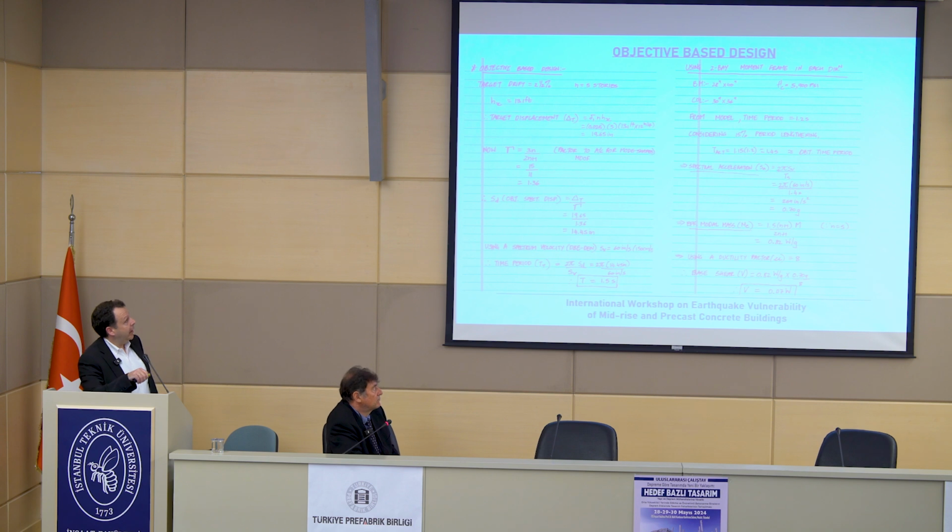Then you need to have an estimate of the sizes that you're going to use for the building. These sizes were selected based on what Bob had shared yesterday, and you also have the SSRP report. In that SSRP report, table 3.2, there are steps to define the initial dimensions, or an estimate of the dimensions, that match this period.